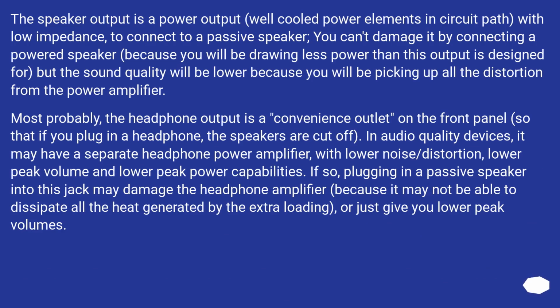The speaker output is a power output, with well-cooled power elements in the circuit path, and low impedance. To connect to a passive speaker, you can't damage it by connecting a powered speaker, because you will be drawing less power than this output is designed for, but the sound quality will be lower because you will be picking up all the distortion from the power amplifier.